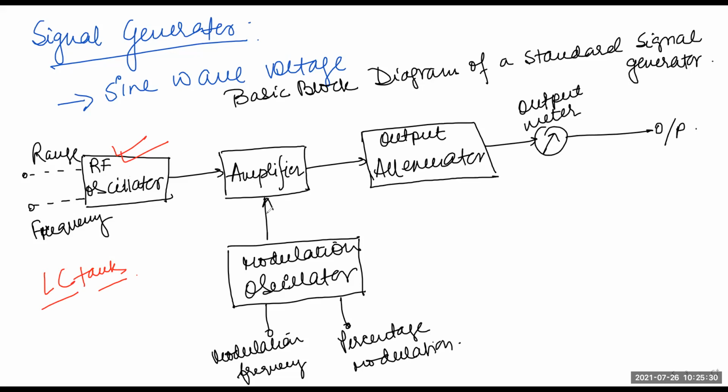Now amplitude modulation is provided here either by an internal or external frequency oscillator. Modulation is done in the output amplifier circuit. See, the amplifier circuit has been connected here, and this is the attenuator, double T. This amplifier delivers its output to an attenuator. Whatever output you are getting from the amplifier is definitely a modulated carrier.